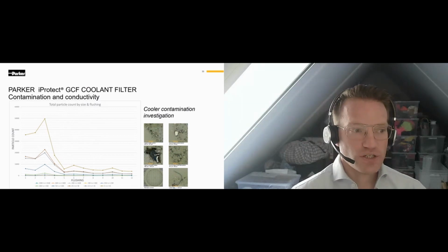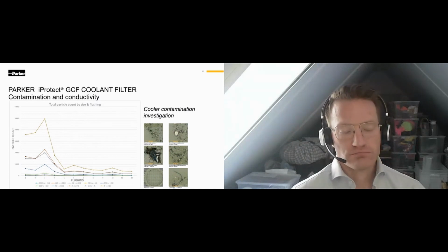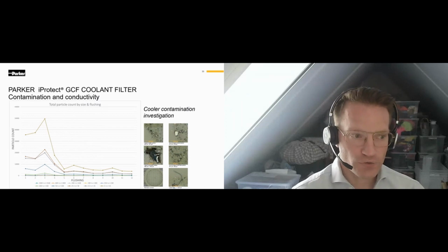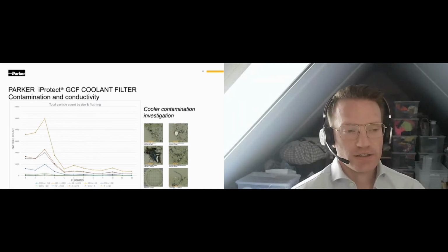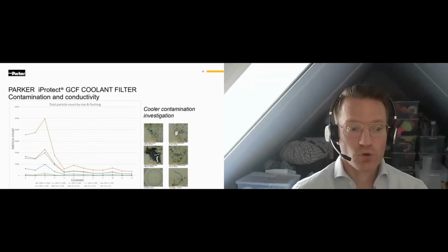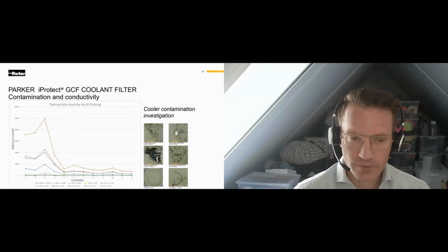In that situation, you actually cannot see those contaminants. So if you have a 150 or 200 micron filter installed on your coolant side, that rough filter efficiency will definitely not capture those small particles. Therefore, we also recommend a much finer filtration efficiency, also to remove those harmful smaller contaminants.